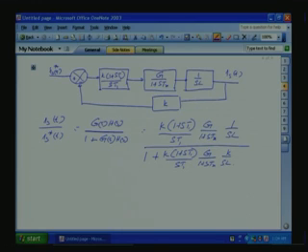So, if you see, the moment the PI controller is added, we are introducing a zero. Here, instead of K, we will make it Ki, that is the current feedback gain. The moment we give a zero, it can give large overshoot, because giving a zero means you are giving a phase lead.